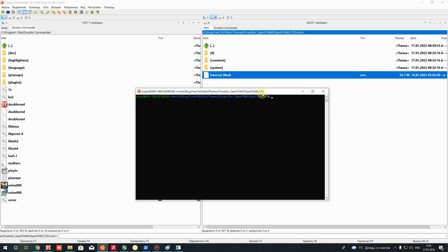And let's go to the path where we have our case with the rotor and stator folders. Here I paste the command ls, and it shows us the folders of the path where we are. Then let's change directory, paste the command, and go to the rotor directory. And let's see our internal mesh here and the different folders of the OpenFOAM case.